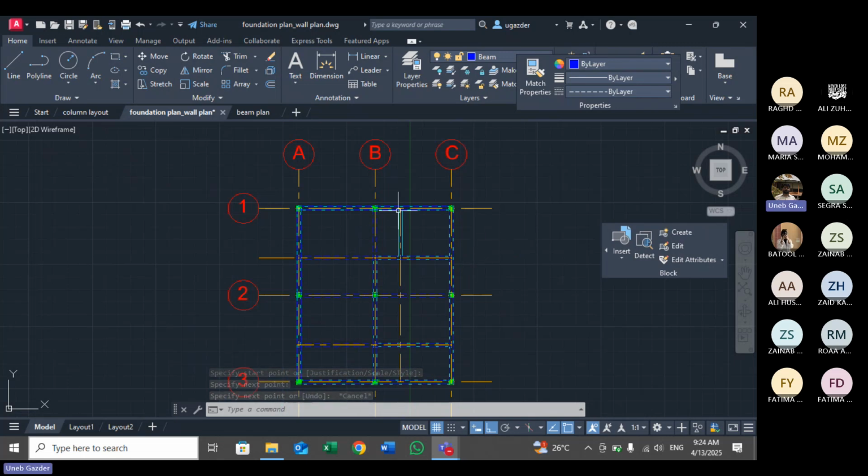As I said, we could have put a beam here, but then one span is very short and the other one is longer. But if I don't give the beam, the span between B and C is the same as between A and B. This is the point. So this is symmetric. So why should I destroy my symmetry and provide a beam here? But this is an option. You can provide a beam over here as well, but I'm not doing it because it will destroy the symmetry.